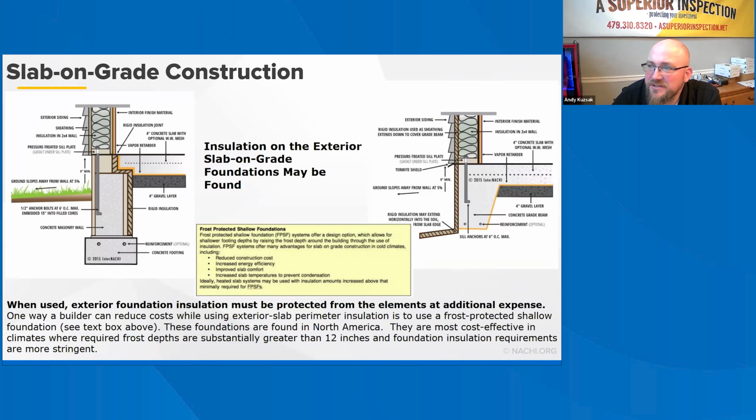As with basement foundations and footings, the local building code may not require horizontal reinforcement of the thickened edge footing of a monolithic slab on grade. The same applies to stem wall and independent slab construction. However, the information in this course describes a minimum of a continuous number 5 rebar located horizontally at the top and the bottom of the thickened edge of a monolithic slab or stem wall.